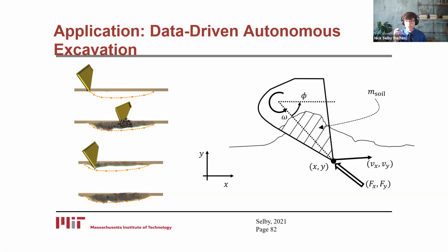So for the data-driven experiment, I worked with Philippos to generate a bunch of training data using a multi-physics simulator called AGX Terrain. We simulated gravel terra mechanics on an excavator bucket with a collection of states like position and orientation, and a bunch of physically measurable observables like the mass of the soil in the bucket and the force of the ground on the bucket. And then we applied the learned lifting linearization to see if it could predict state trajectory over time.